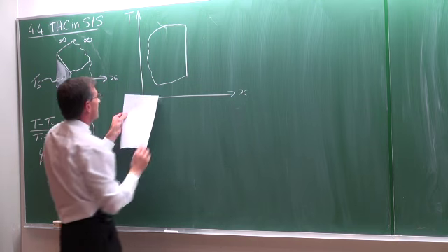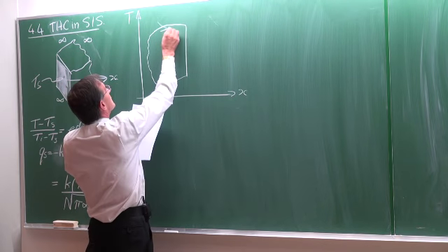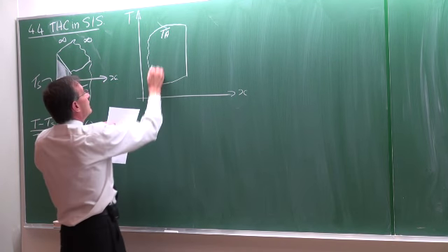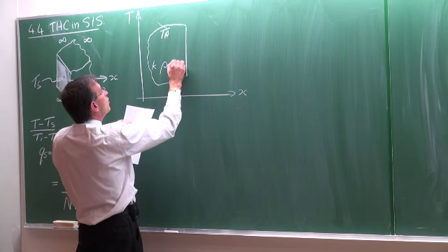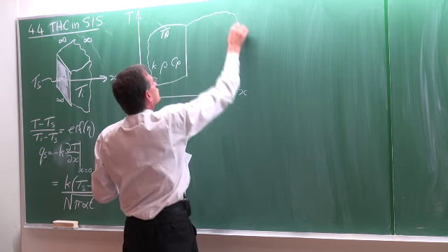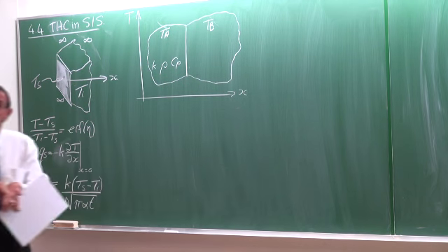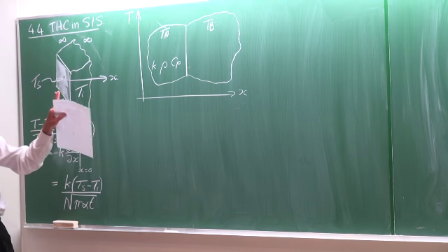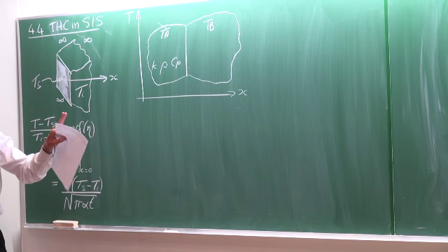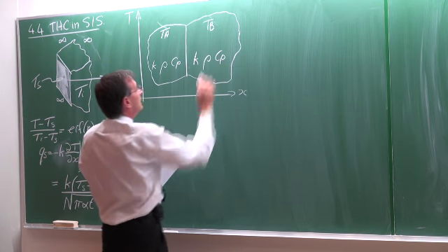Schematically, that is a semi-infinite solid. It has a temperature TA, and it will have properties K, rho, and Cp. Now, that semi-infinite solid touches another one. So we've got two semi-infinite solids touching each other, but with different temperatures: the one at temperature TA and the other one at TB, and their properties also K, rho, and Cp.